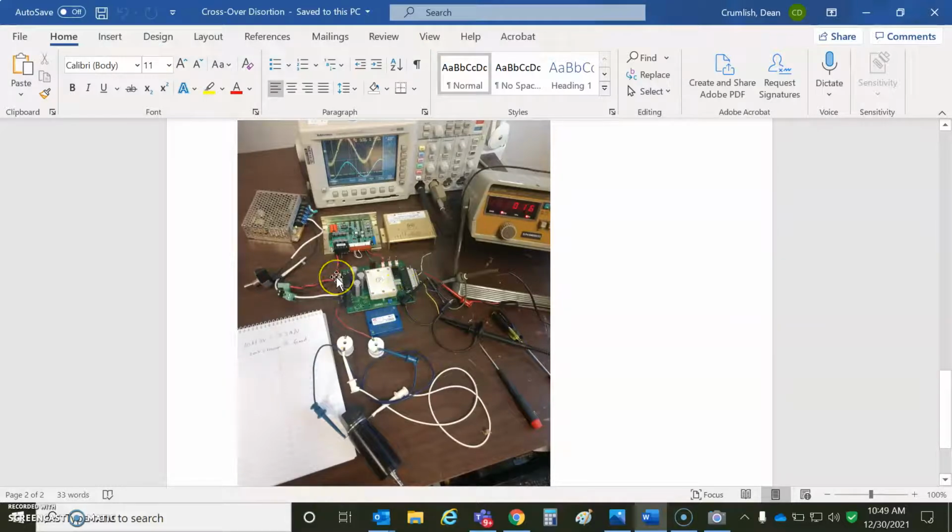And if you had a trapezoidal Hall effect motor, you could hook up the Hall sensors here. We'll send 5 volts out from the 5 volt regulator, and the motor output is normally UVW, but again I'm just hooking up a DC brush motor to U and V.